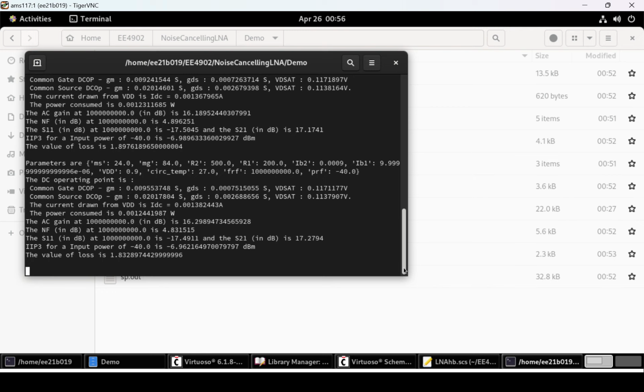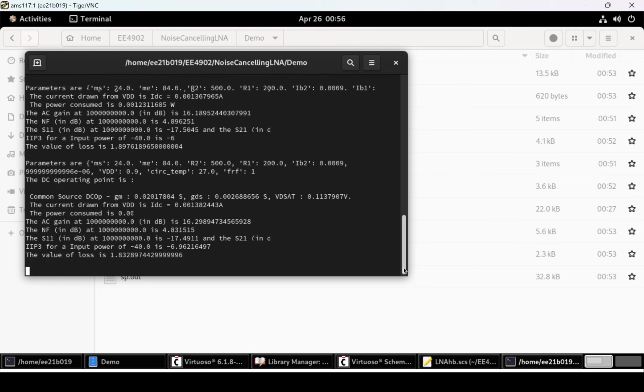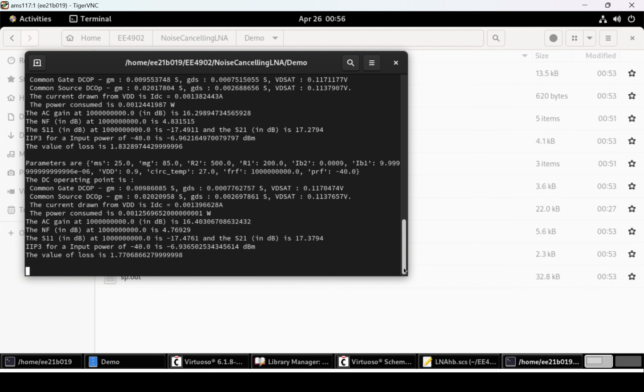The code also picks out the three best netlists. By best, I mean the netlists that have the least loss function and runs PVT variations and sensitivity check on them. And depending on which netlist performs the best, we can pick that netlist. All of those netlists would be saved.